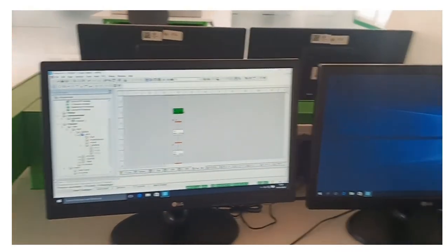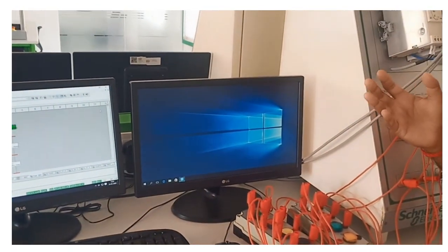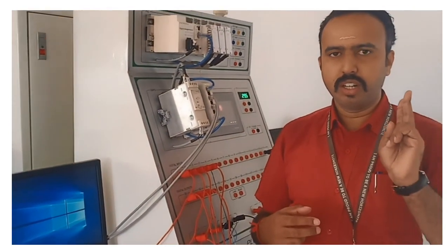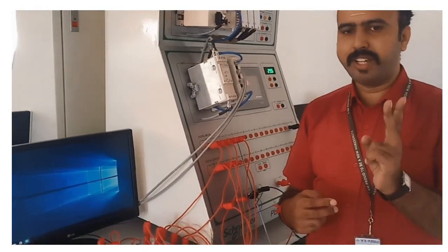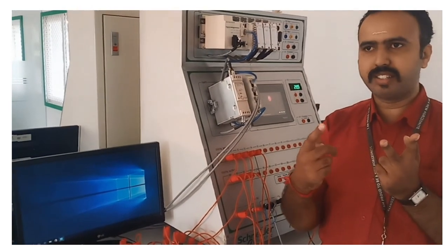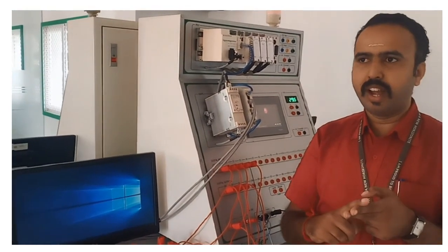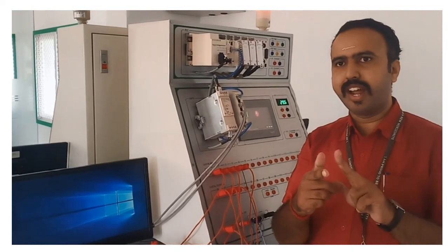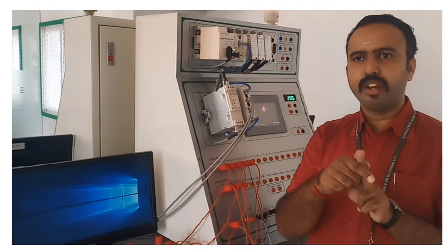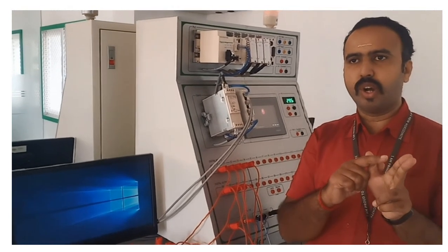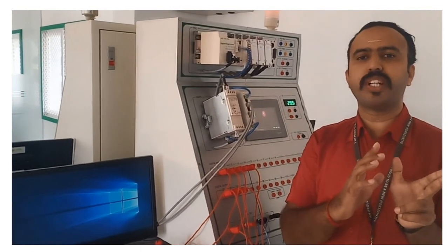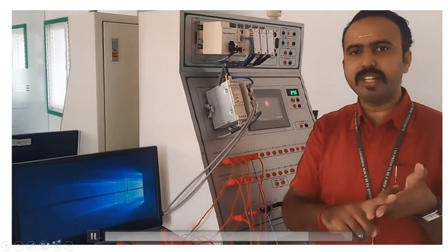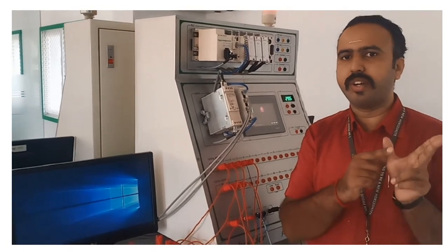So this process can be prolonged as long as we want to try it. But as per our application, we are drilling the workpiece the first time. If it is not satisfied, we are going for the second time. And we are continuing the same process twice. So here we are using a timer as well as a counter. For drilling twice, we are using the timer. And for counting the cycles, totally 4 times the drilling is happening. To ensure that, we are making 2 timers and 1 operate block and 1 compare block.